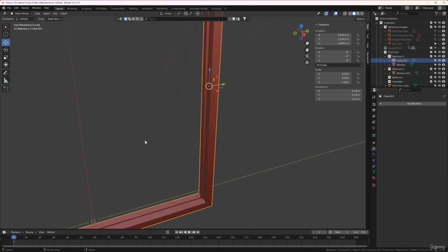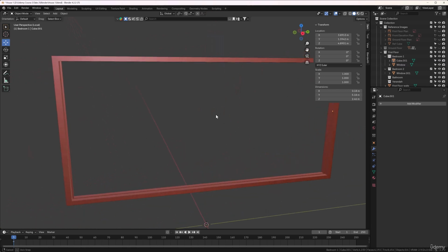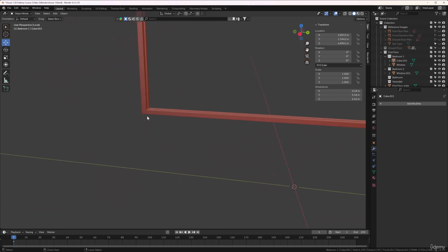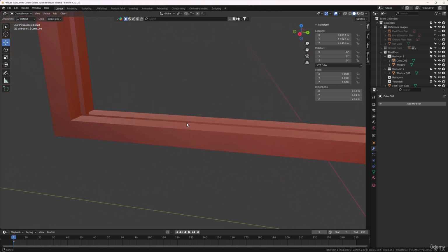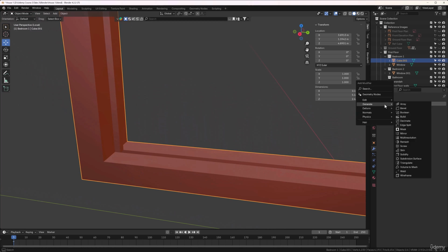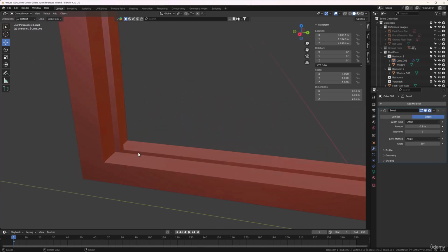Okay, let's tap out of edit mode, and the scale is all right, so let's do that. So Control A, apply rotation and scale, and that's looking good. And let's see if we can apply a bevel to this now and see how it looks. I'll zoom in so I can see what's going to happen. And let's add modifier. We'll grab it first. Add modifier, generate, and bevel. And the bevel doesn't want to work, surprisingly. I thought it would, but no.